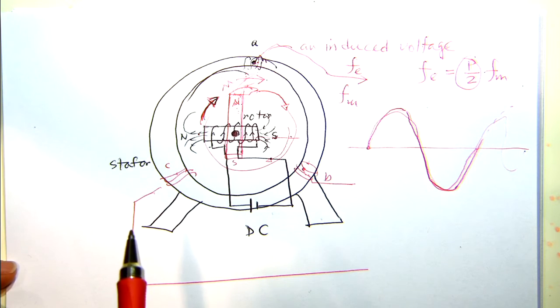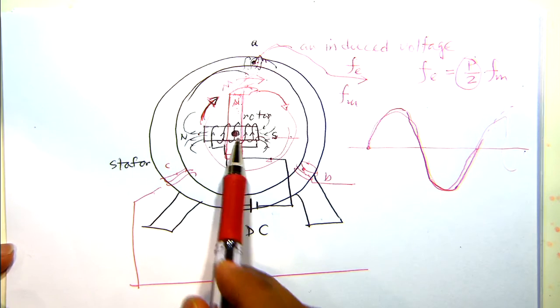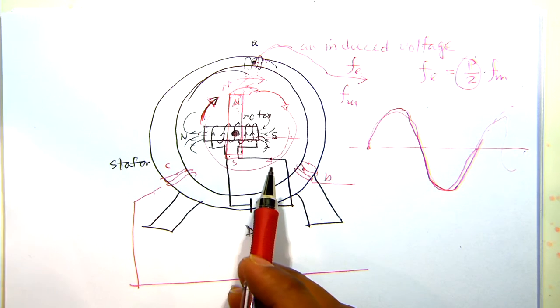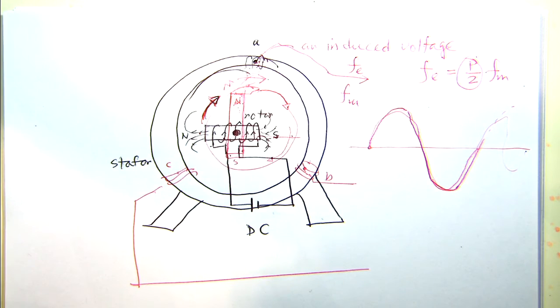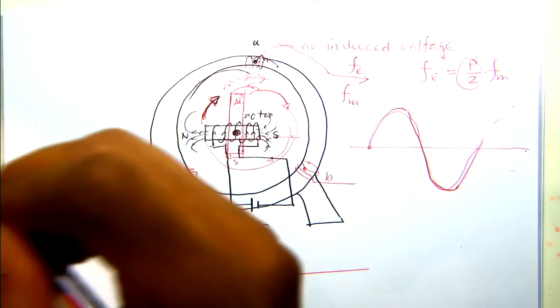So in a synchronous machine, you supply your rotor through a DC source, a magnetic field is created, and then you rotate your rotor by using a prime mover, by some external force. In the case of hydro power generation, you let water down from the hill, put a turbine there, and use that mechanical energy to rotate your rotor.